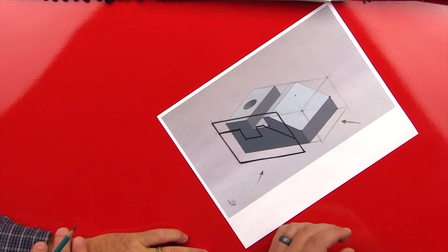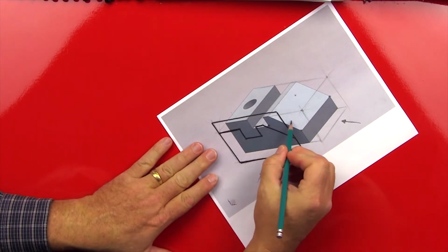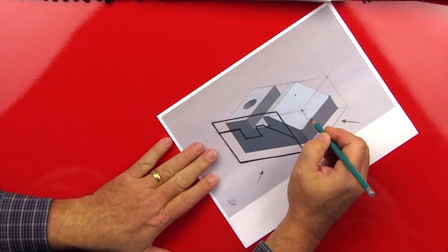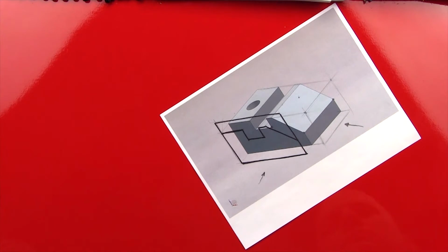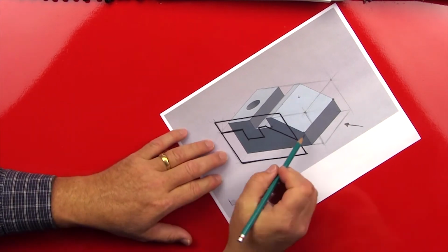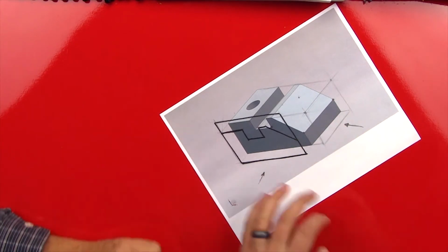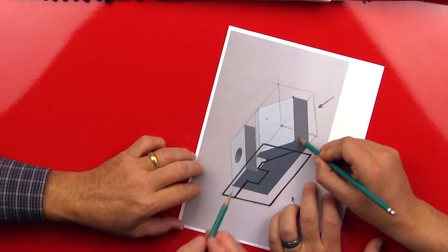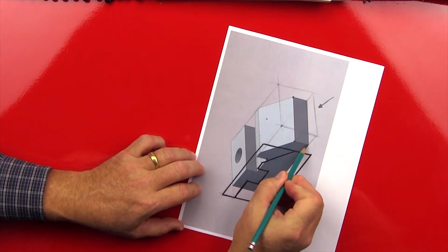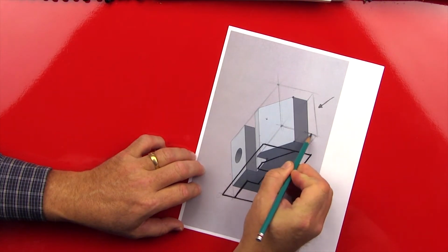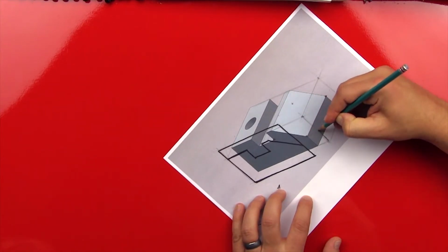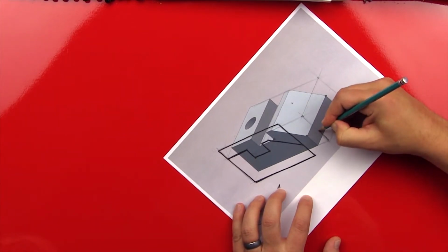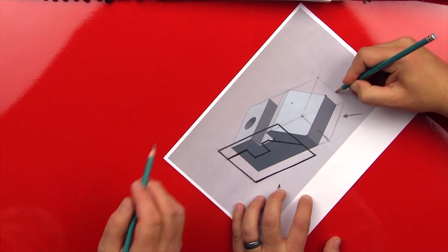Do we want to project that? We could project this line out here, but if we did, we would need to make the line dashed, showing that it's a hidden line. Okay. And so let's go ahead and kind of project this out and that out. It's a little difficult, but what you can do is take this measurement and just bring that measurement out here, because you don't have a perfect line to come off of. Yep. So there. And you can do the same back there.